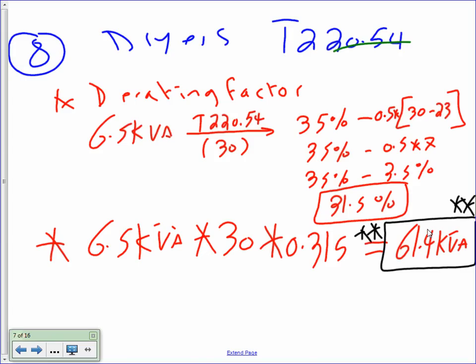If you multiply them all and then you cut them by 31%, down to 31% of what they used to be, that's substantial. If I cut your salary where you work down to 31%, would you be happy? You'd be mad, right? So 31% is a lot of derating, guys. Can I get you, Andrew, to understand the gravity of what we're doing? This is what distinguishes a designer from a drafter. Designers understand why we are doing what we're doing, to try to reduce the size of a service. Cool? Aaron, my friend, does it make sense?